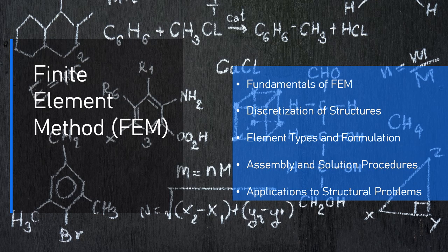4.3. Special elements. Beam and truss elements are often used in the analysis of frame structures. They are capable of handling axial forces, bending moments, and shear forces. Shell elements are used for thin-walled structures such as roofs, plates, and shells in 2D or 3D problems. Shell elements can account for bending, membrane forces, and rotational effects.